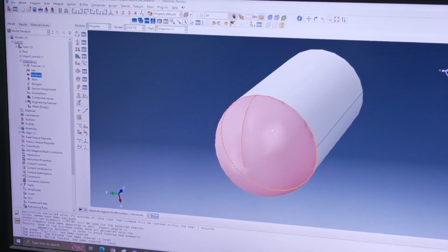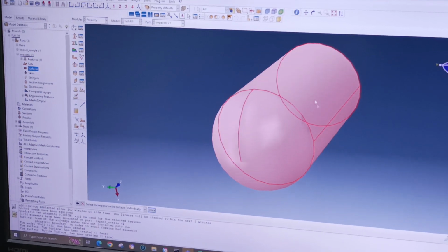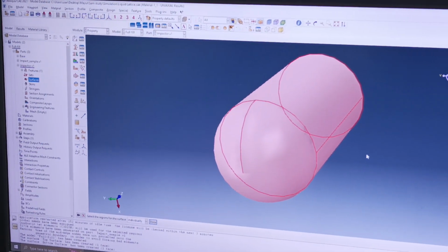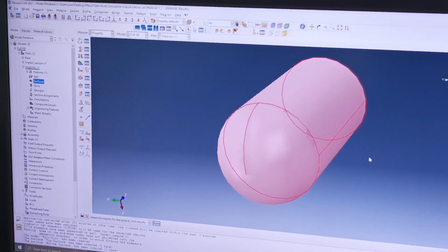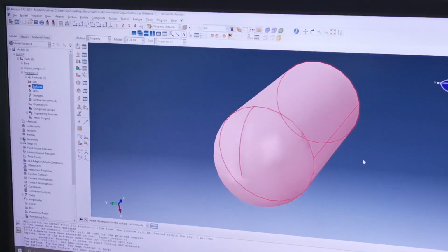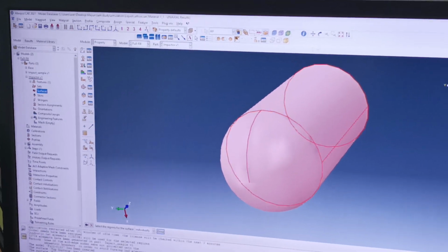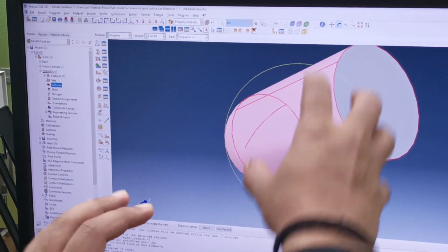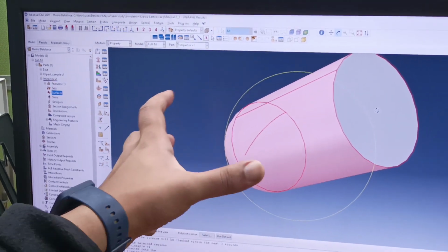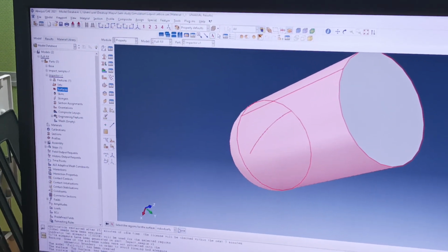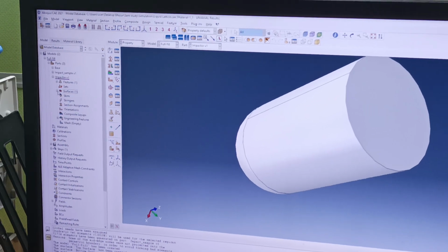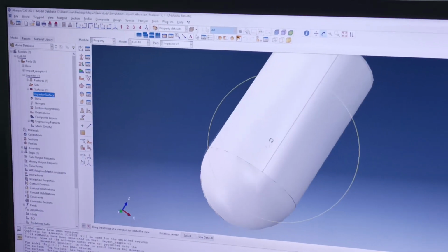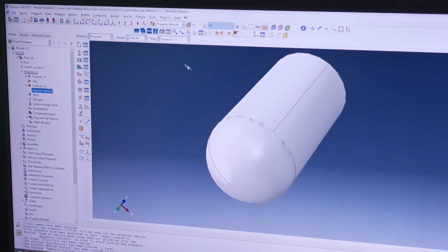So I select this front surface and this cylinder part, because when the punch goes down, this part and this will touch it, because the sample becomes like this, right? You will wrap it. So we don't select this because it's of no use. This is totally long like this, so this is just a prototype for that. And click on done. So now we have the impactor surface also. So we are all set. We created all the surfaces.